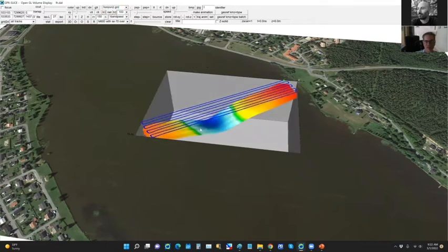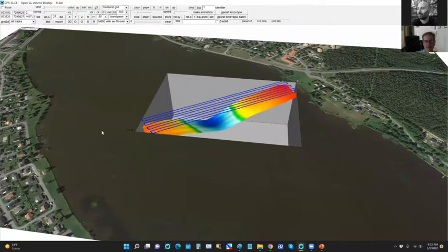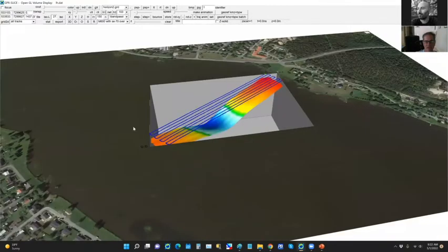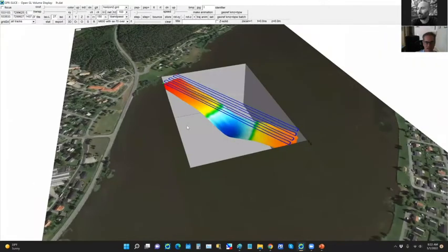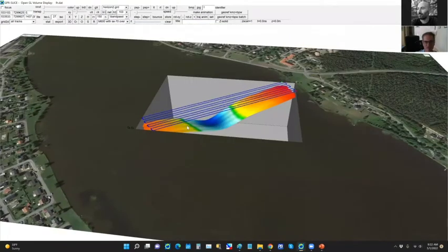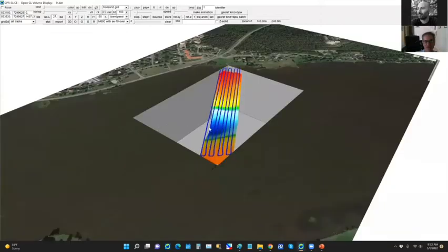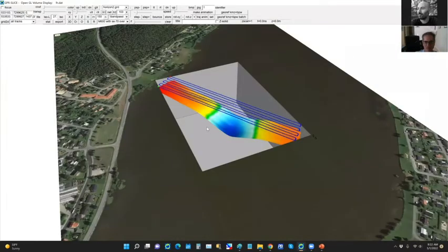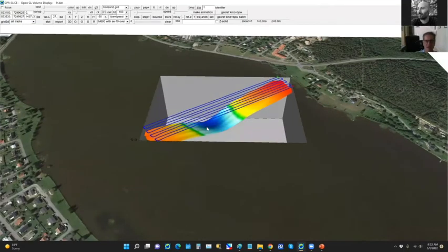And there's the actual bathymetry of this frozen lake. It's very unique that they were flying at a high elevation, but radar waves are so unique that if you have frozen fresh water, you can get radar waves through the frozen lake and get down to the bathymetry at the bottom of the lake and get returns that you can process and do bathymetry from a drone. Okay, that's all we want to talk about Horizon. Next, we'll be talking about topographic adjustments in GPR slice software.